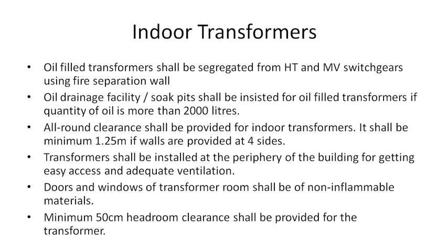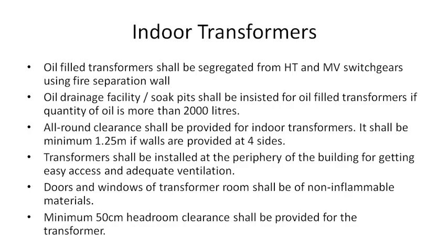Then a minimum 50 centimeter head clearance is to be provided for the transformer. If there is a roof, from the top point of the transformer to the roof, a minimum 50 centimeter headroom clearance must be provided for the indoor transformer. So these are the various requirements related to indoor transformers.